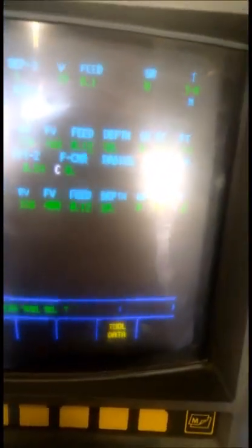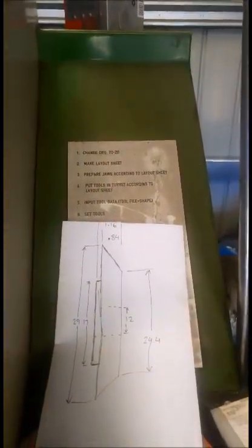Finish, we don't need a finish because we're just going to do it in one cut. And then just auto for speeds and feeds. Now we only need a roughing tool on this because we're not running a finish cut, because obviously once it's roughed it, the part's fallen off anyway, it's all done. So start corner, we don't need a start corner. Starting point in X will be 17, because that's my step. Starting point in Z will be 1.16, which is the edge of my part there.